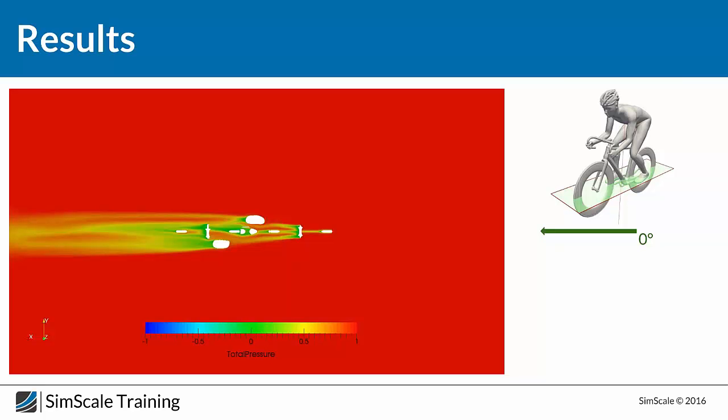Exactly. And just to give you the formula for why we need a turbulent boundary layer: we have tau, the shear stress, equal to mu, the dynamic viscosity, multiplied by the gradient of velocity. If we want to increase our tangential effort on the surface, we need to increase either the dynamic viscosity, which is not possible unless you change maybe the temperature of the fluid, or the gradient of velocity in the y direction, the direction perpendicular to the surface.